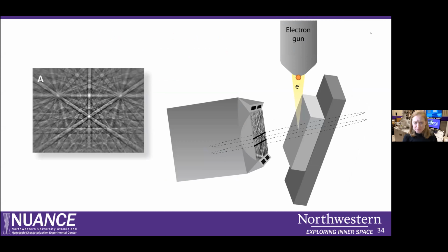Paul, can you click? The electrons are diffracted from the sample along the crystal lattice, or the planes in the crystal lattice, and hit our EBSD detector. As it diffracts, it creates diffraction cones, which are at such a low angle that when these cones hit the detector, they appear as lines. You can see it kind of looks like there's 3 lines there.